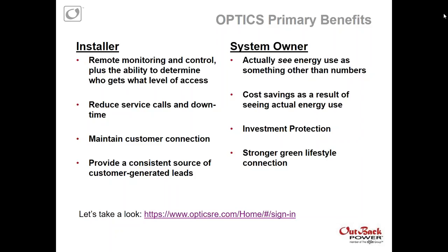As an example, you have 80% of your battery left. You told your battery don't go below 60%. You've got a peak rate that you go into at noon, and you tell the system to start going off the battery because you're getting charged peak rate. Well, you've already told that battery, when you hit that 60%, stop using HBX, or whatever mode we were using to take you off the grid. So you would automatically put the loads back on the grid.